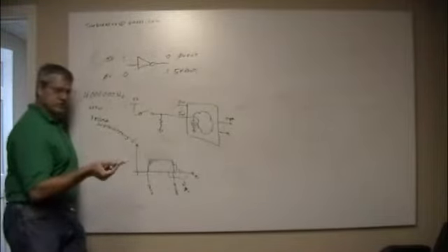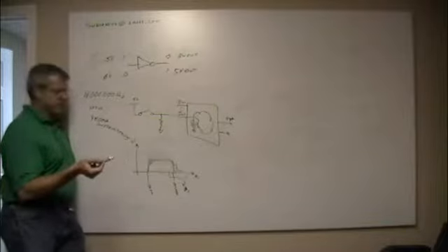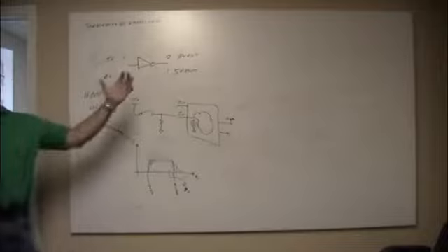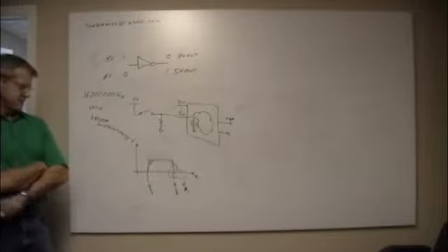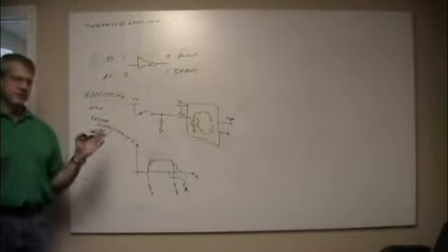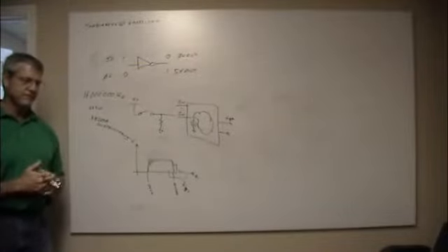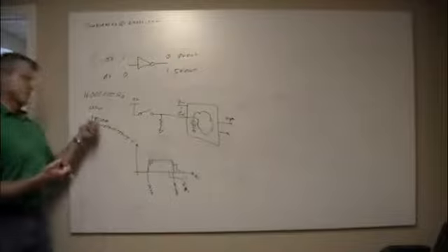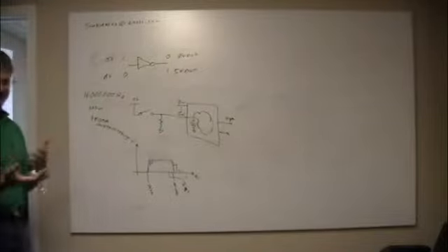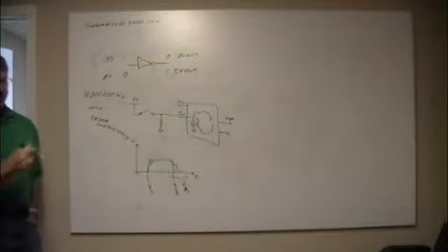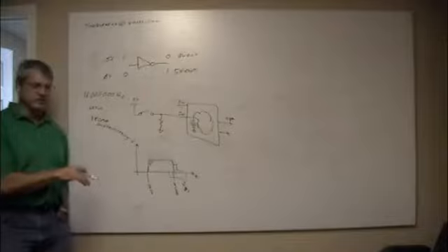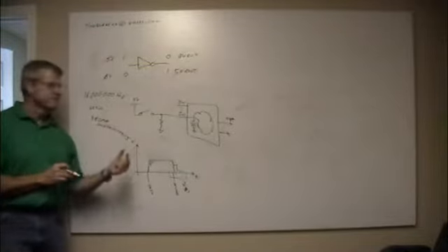Practically speaking, there's two ways you can do this. One is you can go in the software and put in a really big buffer and say, if I saw one of these within this time, I know that it shouldn't happen. But what you're doing is wasting 48,000 instructions that you could be off doing something else. There are cleverer ways to do it than that, but you're wasting some number of instructions to debounce that switch.